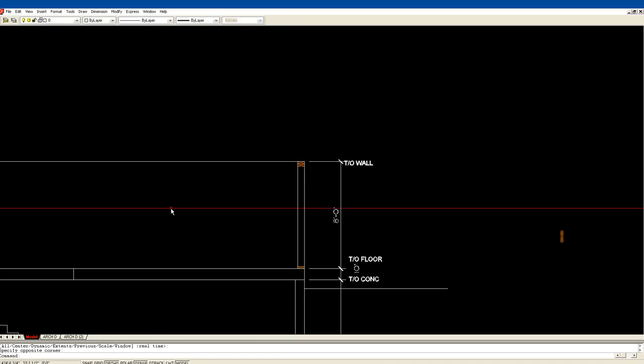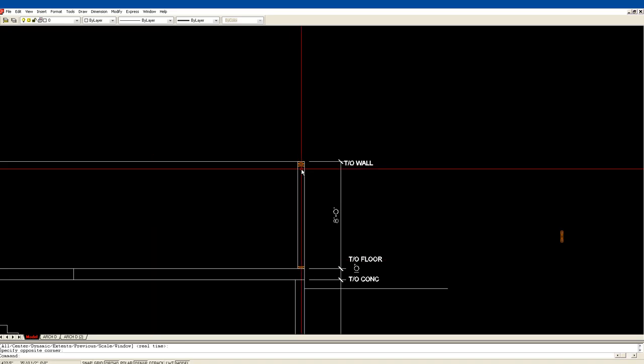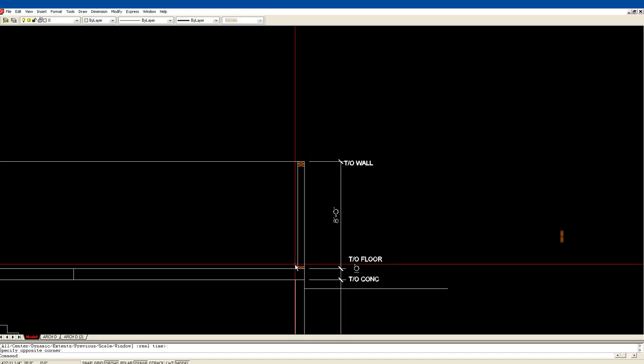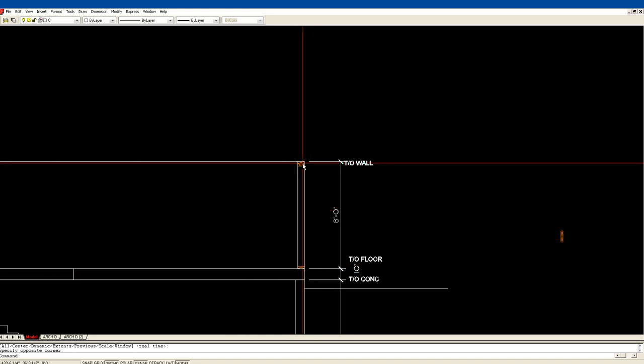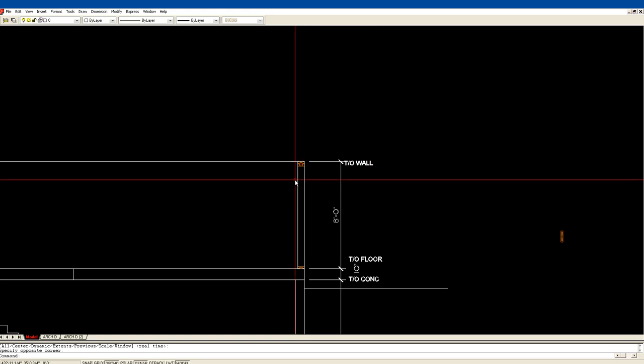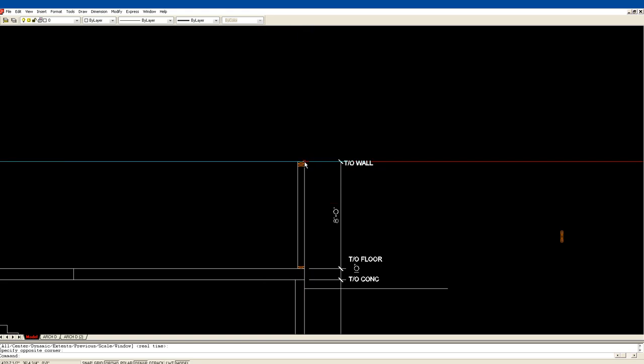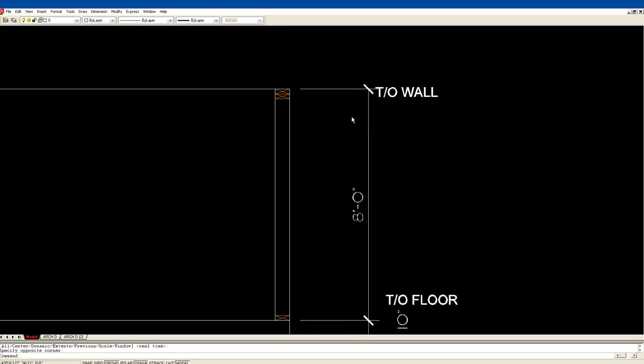Of course, they'll have the wall laying down on the floor, and they will apply the top plate, the bottom plate, the studs in between, lay out all their windows and doors and so on and so forth. Stand it up, brace it in place, and then lock all the sections together with this locking plate at the top. So these studs in between run from the bottom to the top. They are less than 8 feet, obviously, for an 8-foot high wall, about 82 inches.